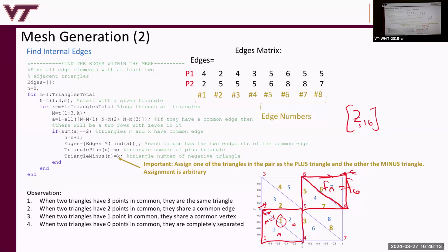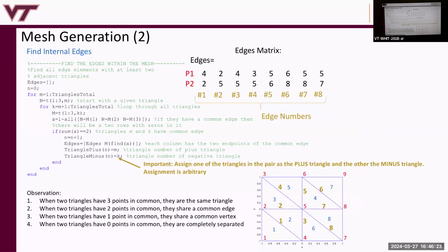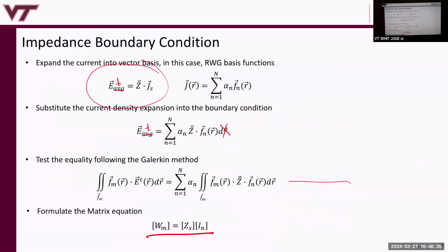That means when it comes to calculating impedance, we don't care about other triangles. Yeah, that's good, this is a local boundary condition, right? It doesn't care about what's going on on other parts of the scatterer, on the other side of it, right? It's a local phenomenon. The relationship between the current density and the total field there is locally the impedance, right? Point-wise.